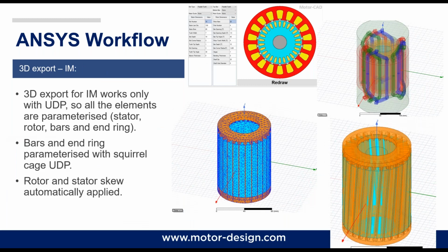As I already mentioned in the previous slides, for the 2D export, the 3D one for induction will be available in the next MotorCAD release. And as it is for the 2D, every component will be parameterized for the induction motors, such as a stator, rotor, bars, and end ring. In the 3D, there's no need to assign the end connection option to model the end ring and connect all the bars, since we are using the squirrel cage UDP to model bars and end ring. Also for the induction motor, the skew for stator, rotor, and bars will be automatically applied, since the use of UDP makes the implementation easier.